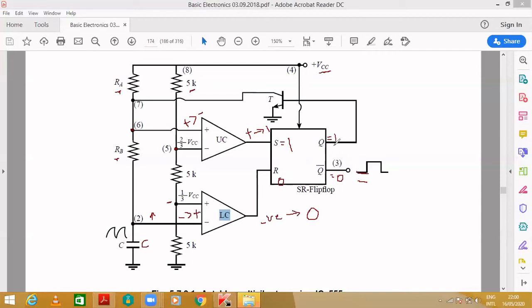When this becomes 1, the transistor here, this is the base of the transistor. So the IB, the equivalent current, will be generated, and when IB starts increasing, IC will also increase. As per the equation, IC equals beta IB. As IB increases, IC also increases. So when this IC starts increasing, what happens? Whatever current is flowing will start flowing towards this, isn't it?